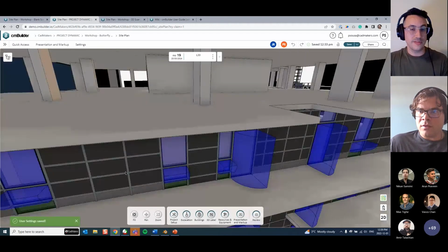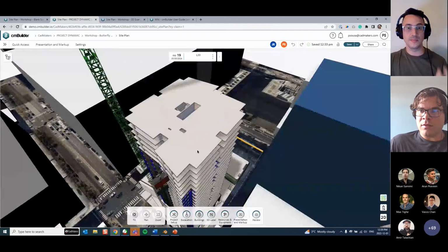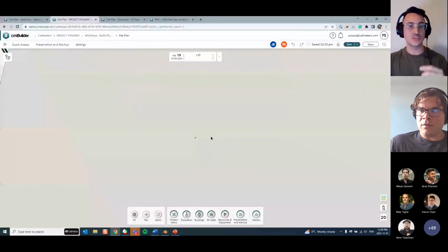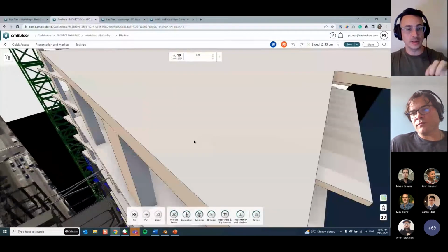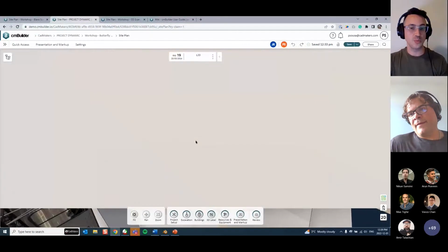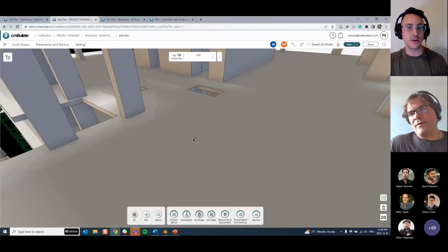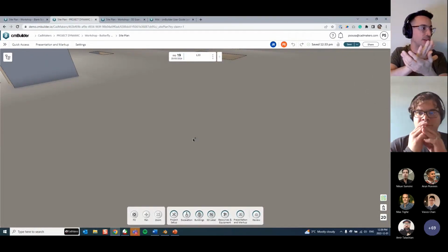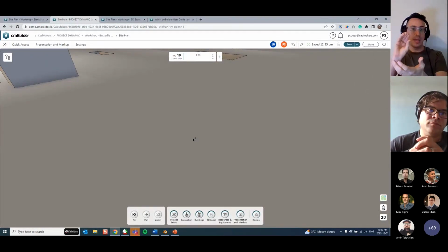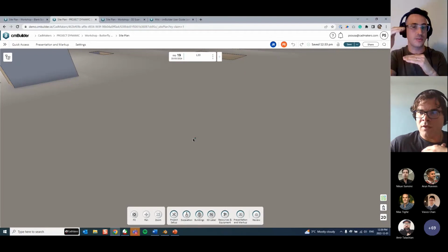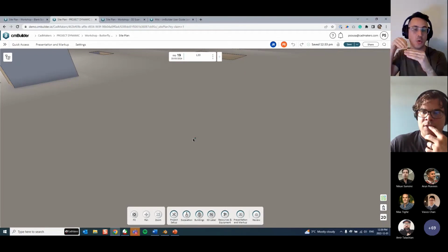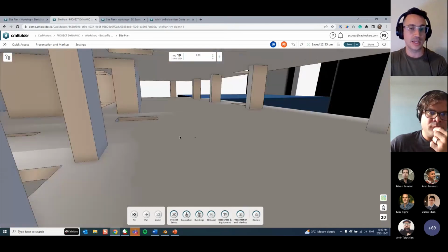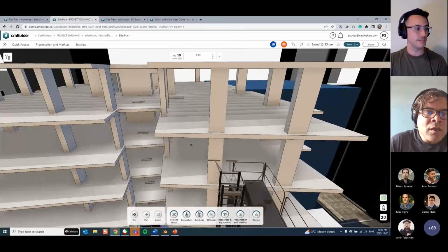Another thing I've noticed from users is that they try to zoom in on a specific location and then the zoom gets super slow. It's something called harmonic zooming, where as you get closer to the geometry you selected as your center, we reduce the increments of the zoom, so you won't go through it too quickly. You can just reset that by middle clicking and then zooming in and zooming out again.